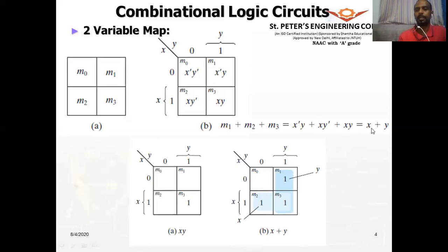If less circuits, less delay will be there, because the output has to propagate from one gate to the other when we have cascaded them. So therefore, the delay also is reduced. So this is an advantage why we use the mapping technique and why we have to reduce the variables.